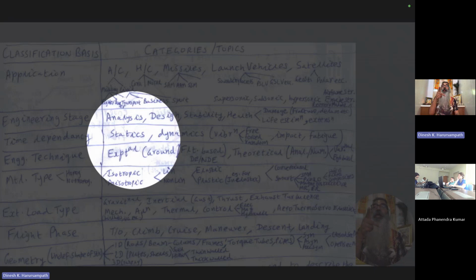But even those three dimensions, in fact, we will cut out one of the dimensions, as I was showcasing in examples in the very first class in the aerospace engineering department, where we said that if one of the dimensions is small, like if it's a plate, then we will essentially be leaving out the thickness, and therefore when we leave out the thickness, it's only the breadth and the length that come into picture. Once again, if we deal with this as a beam, we will leave out not only the thickness but also the breadth, because both the thickness and the breadth are small compared to the length,